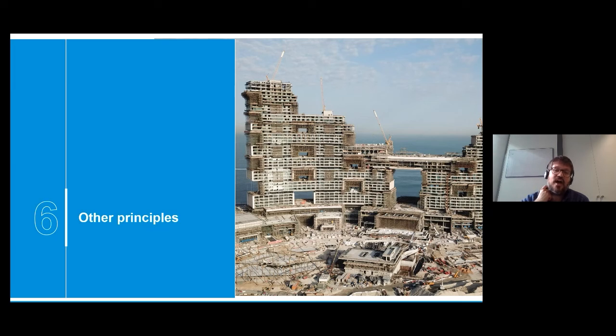This depends on how they are doing it, because if they take the sea sand and keep it in storage outside for a long period, just by the rain, it will be washed from the chlorides. But otherwise, you can always wash the sand. It goes through a whole mechanism with a lot of water to remove the chlorides from the sea sand. So totally correct. Thank you. And you also have to be careful with the shells that you can find in the sand, because it's not that good for the strength.